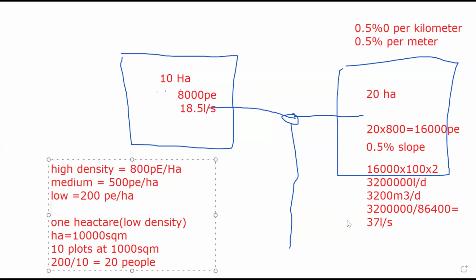Understood? So now I just wanted to finish up this. So somebody go to your nomogram, open your nomogram. Let us design these 2 pipes. Let us get the size of these 2 pipes. If that is what somebody gets today, I think it is still worth it, especially for those who didn't really come last week. Those who came last week already know how to do pipe sizing. I'm still coming to that assignment.